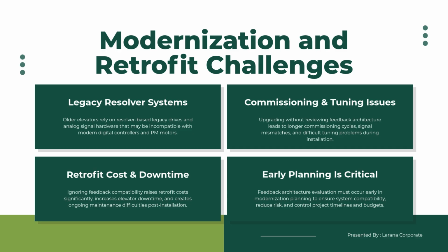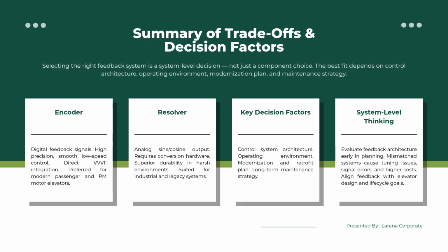When resolvers still make sense. Resolvers are still useful in elevator applications where the environment is difficult. For example, if the elevator operates in a place with severe vibration, dust, oil contamination, large temperature changes, or long industrial duty cycles, resolver durability may become more important than advanced positioning refinement. In these projects, stable operation over long service periods may matter more than ultra-high feedback resolution. Resolvers can also remain practical in legacy systems that were originally designed around resolver-based feedback. Replacing the resolver architecture may not always be simple, especially if the drive, controller, wiring, and conversion hardware are all designed around that system.